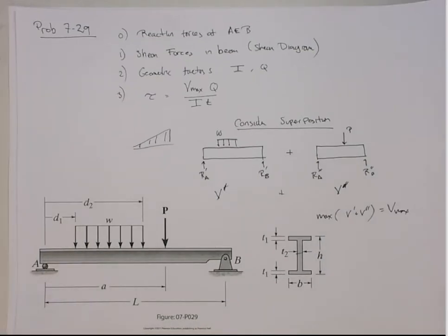So we'll kind of break them up into two cases. And then if you wanted to add, like I said, other types of loads to the program, you can add that later on. And of course, you could take a similar approach to computing the bending stresses, right? We're going to do shear stresses, but you can also do the bending stresses. And if you want to do the bending stresses, a nice little trick, maybe I'll do a video as well, is you can just integrate the shear moment diagram. Once you get that in a program, you can integrate that and get the bending moment diagram. Right? And figure out where the maximum bending moment is, and then compute the bending stresses off of that.